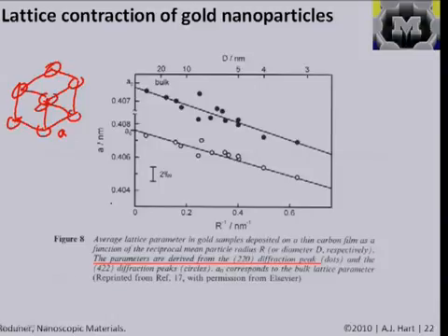And you can see that these changes are pretty small. We're looking at 0.4 nanometers or 4 angstroms here, and it's like 0.0406 to 0.408. But there is a change, and it looks like a pretty linear trend. This also shows that using diffraction, the interaction of X-rays with the material, you can get a pretty precise measure of the spacing. And this is simply because as the particle gets smaller, there's more pressure inside, and therefore you're physically squeezing the atoms closer together.